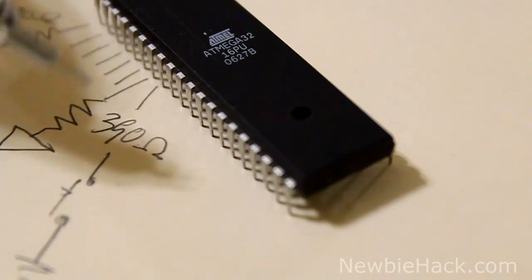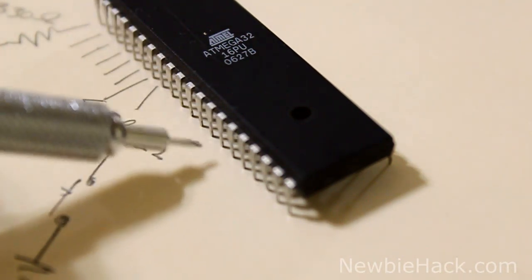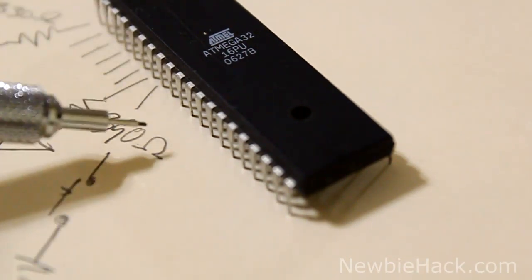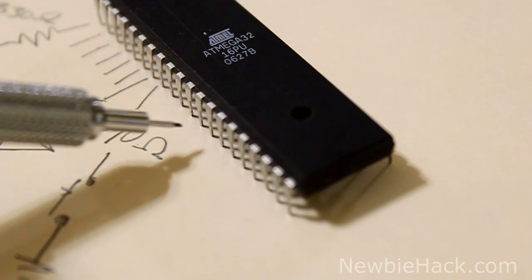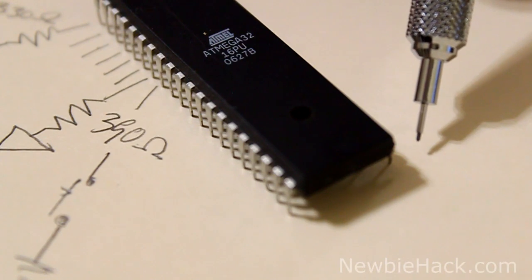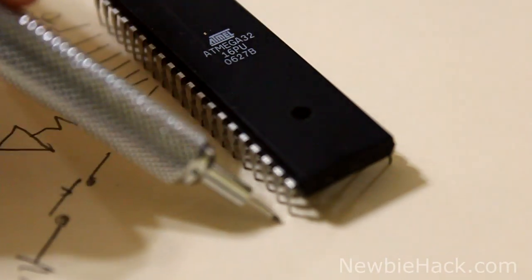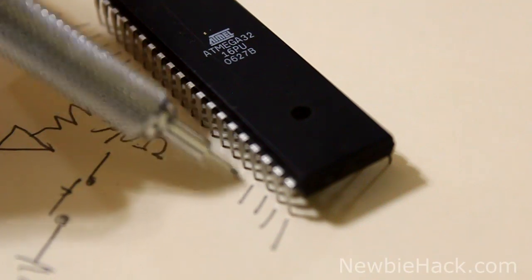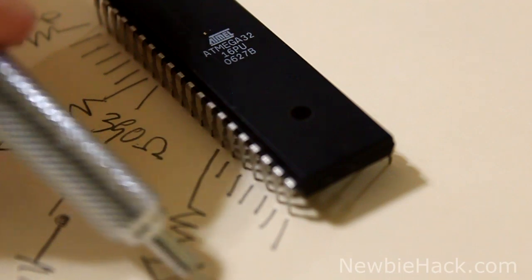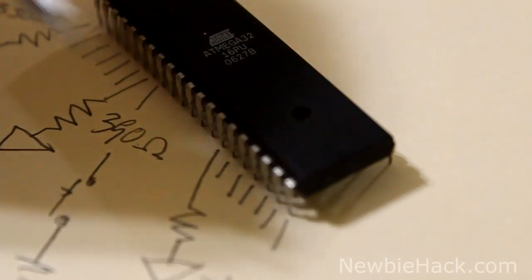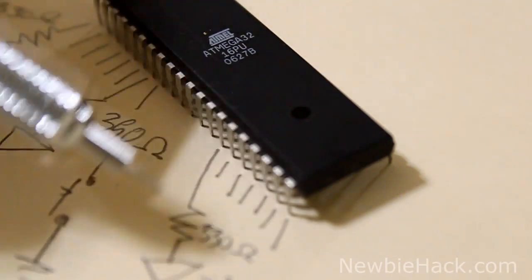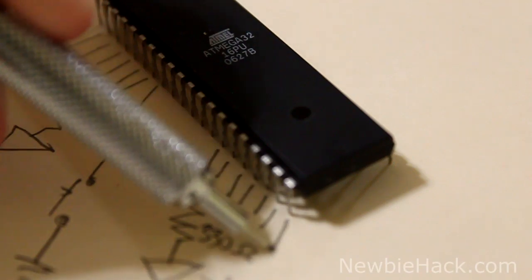On the Atmega32, port D actually has 7 of the pins here and the last pin on the other side. The setup is going to be pretty much the same. You're going to have 7 LEDs, and then on the other side, which is pin 8 for the port D, we'll have the button. So let's go ahead and count this out. 1, 2, 3, 4, 5, 6, 7. We have LEDs, and each one of these are the same, 330. You can have a greater level of resistance, it's just going to have a dimmer LED. And then this one is the red one.